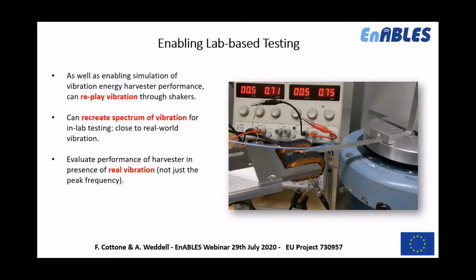We can also play back vibration spectra through our shaker, so we can replay the vibration that we've captured from the real world through our shakers, so that we can do a realistic test in the lab, which gives us a good idea of how that harvester is going to perform in the real world. So we're not just looking at peak frequencies and amplitudes, we're replicating the spectra of the vibration signal.